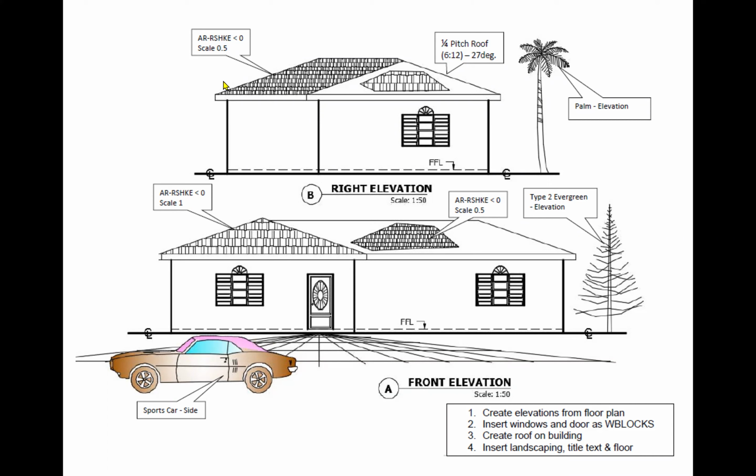And because it's a hip roof that we had done in plan, not a gable roof, we're going to be seeing this portion of the building showing the hip end and this section over here showing the same thing but sideways. And if you look from the right, this line that is slant up here in the right elevation will be the triangular portion up here, and the side here now would be the side of that hip roof.